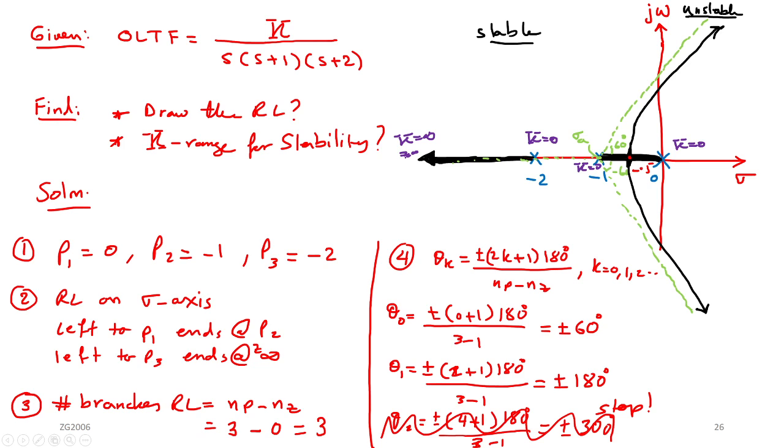We call it 0 at infinity. Okay. When k equal to infinity, it will go to 0 at infinity. In fact, the root locus always starts at the pole when k equal to 0 and always ends at the 0 when k equal to infinity. But we do not have 0 here, so we will imagine there is far away 0.